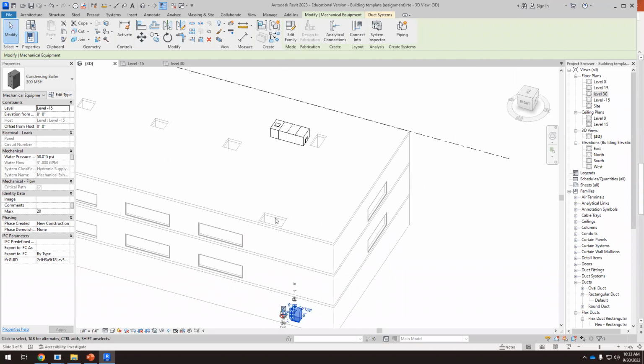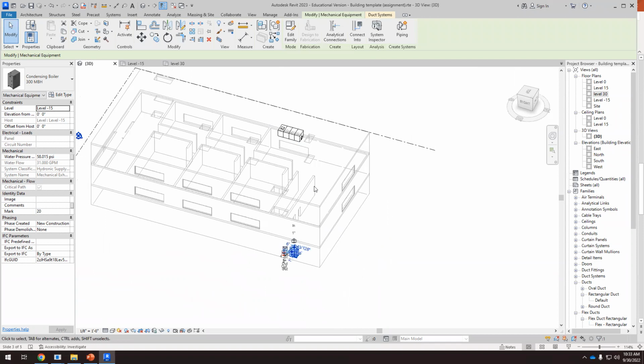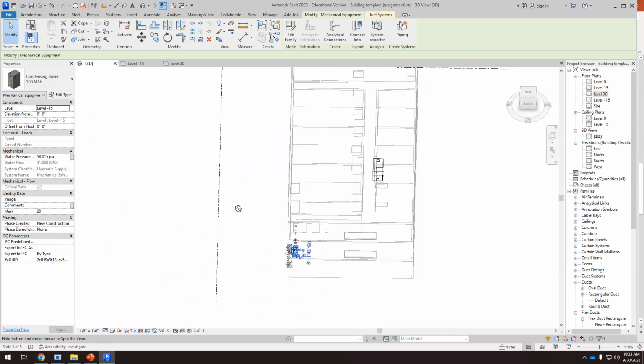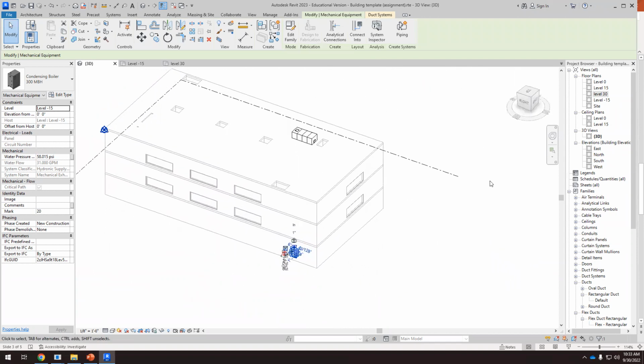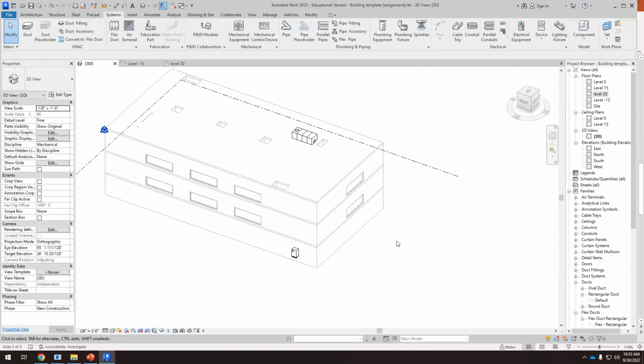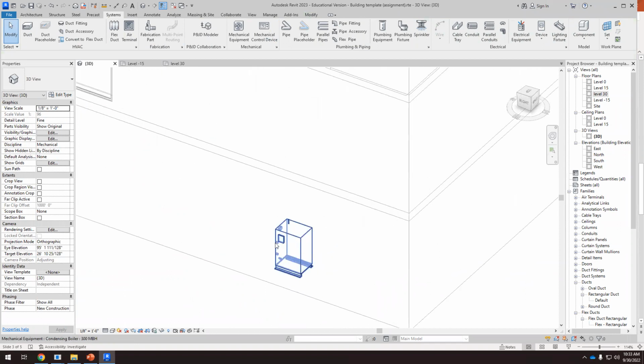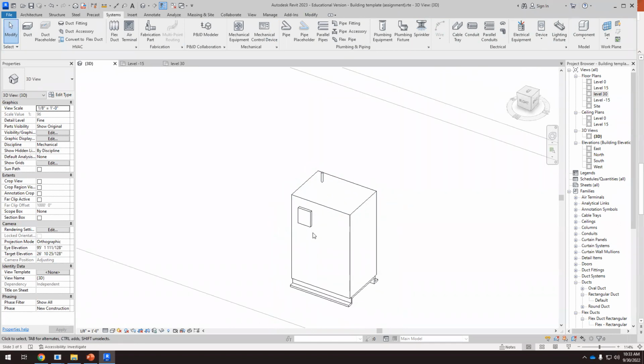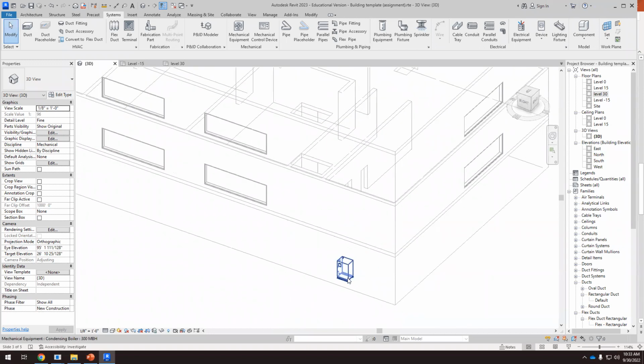And then I can go all the way to the air handling unit. I wouldn't do that, because another rule of thumb when we are designing pipes and ducts is to minimize the amount of pipes or ducts that we have outdoors. Having all these pipes outdoors, we're spending a lot of money and energy on heating up the water.